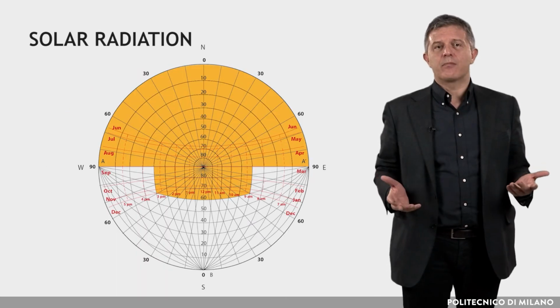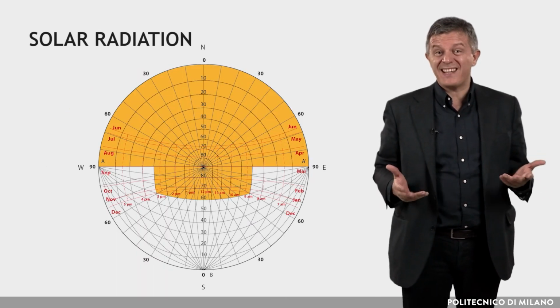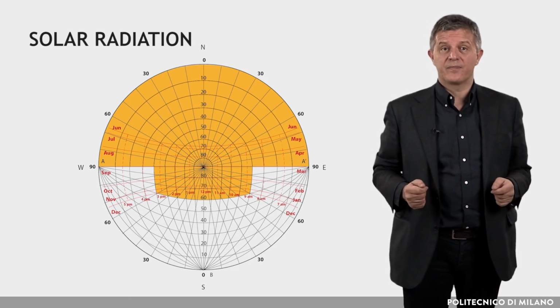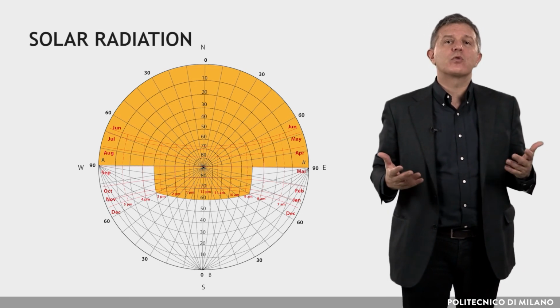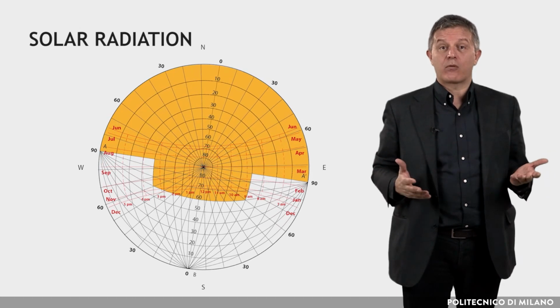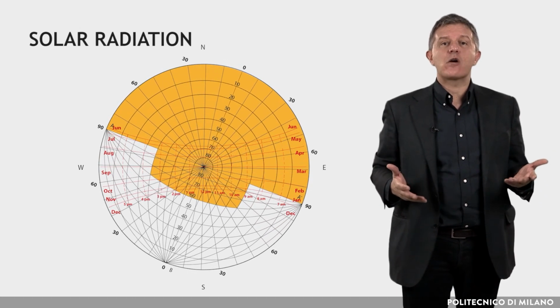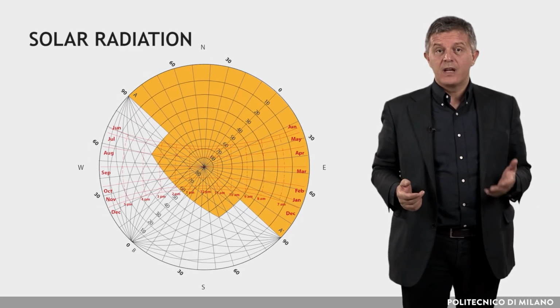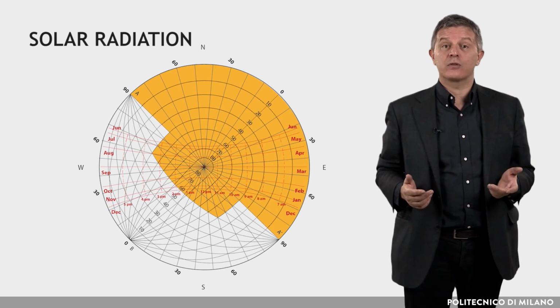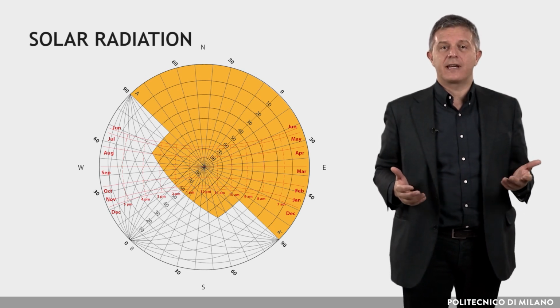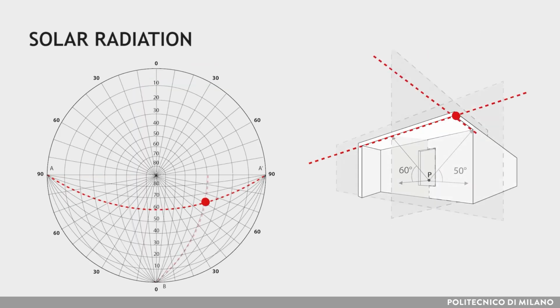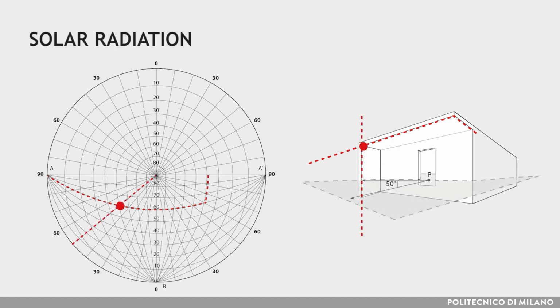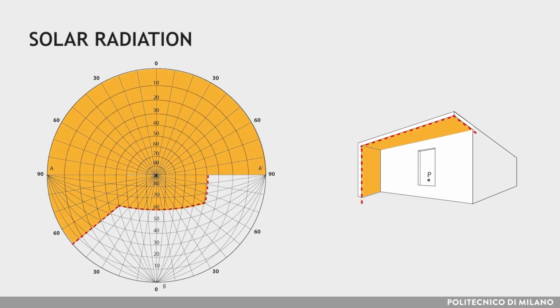In the previous examples, situations corresponding to facades exactly south-oriented were shown. It is, of course, always possible to consider any other orientation by rotating the protractor and aligning the lower vertical semiaxis with the normal to the facade. So, in this picture you can see how a horizontal obstruction on a southwest facade is plotted. It is also possible to combine the coincident effects of vertical and horizontal obstruction by reading on the same diagram the relative values of epsilon, sigma and omega.